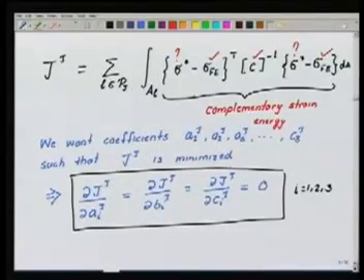And you see what again is the advantage, let me reiterate it, that here we are solving small problems over each element. For example, here the size of the problem is 9 by 9. Solving these small problems does not take any time. In fact, it takes negligible time with respect to the solution of the actual finite element problem. So this job gets done very quickly as compared to the cost of obtaining the finite element solution. And that should be one of the criteria for deciding whether a post-processing technique is going to be useful to us or not. If I spend a lot of effort in post-processing, it's better to resolve the solution with a higher order approximation.